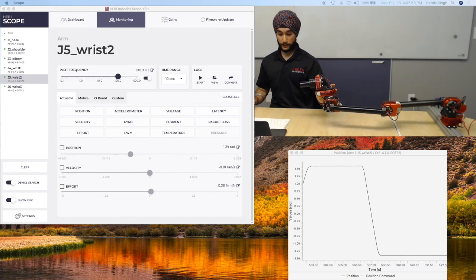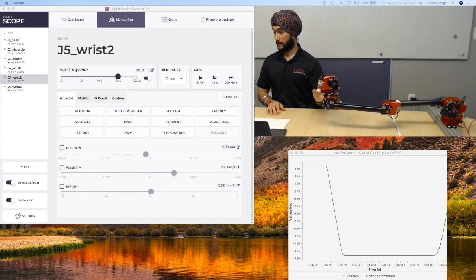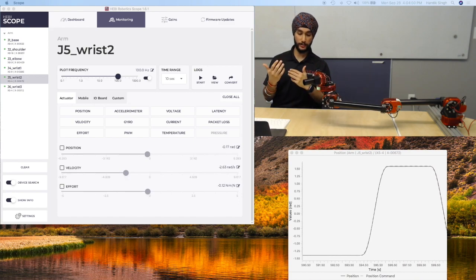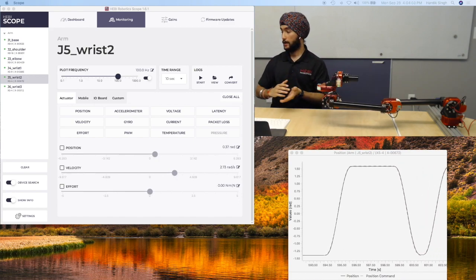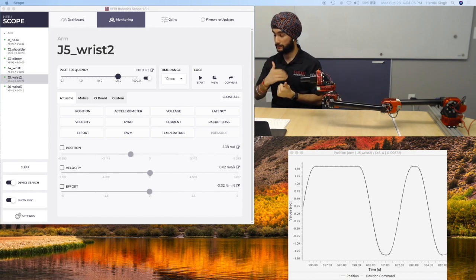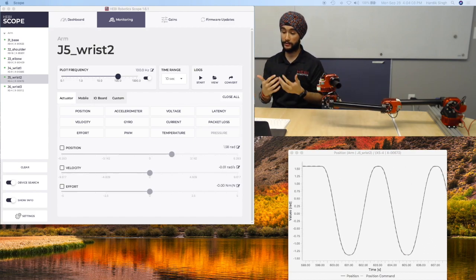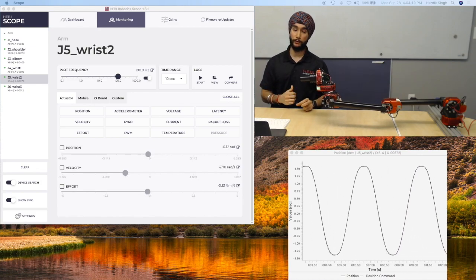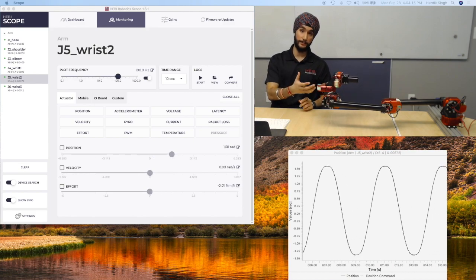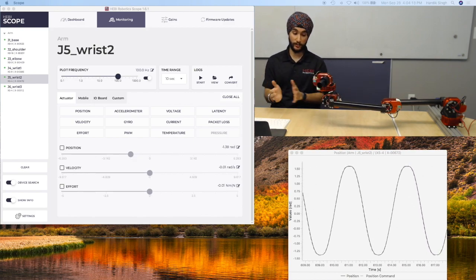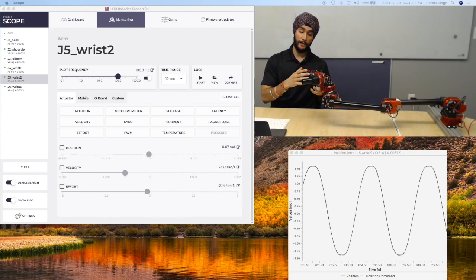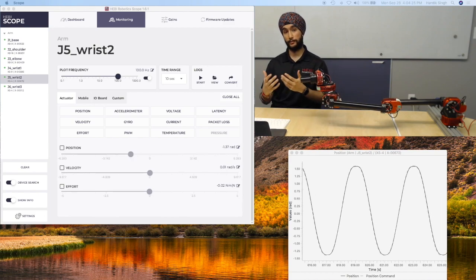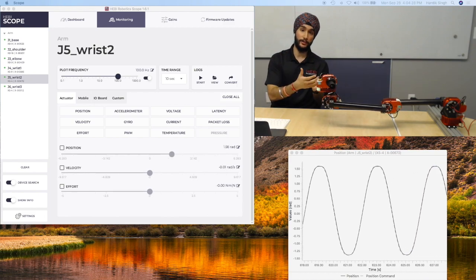Now, I will set these waypoints to run by themselves. And I really want you to take a look at, firstly, how this motion is a lot more in control. That's one thing. But on the graph, you're seeing that the feedback, the continuous line, the ability of the actuator to stay on track to the motion that we want is much, much better when we've created a trajectory from the desired positions. I haven't done anything else other than still set positions, but in this case, the positions are being fed into a trajectory generator that creates velocity, acceleration, and position profiles for the actuator to follow.